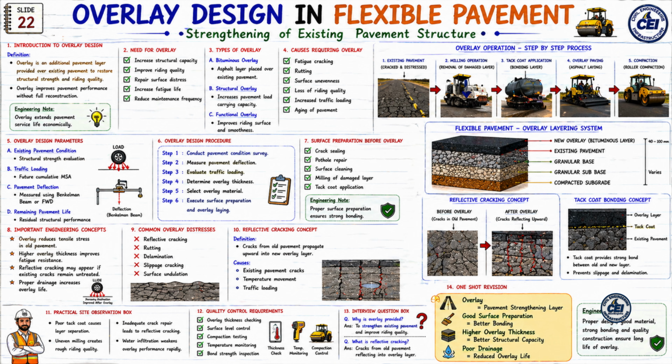Now let us look at the second topic. No need for overlay. Overlay needed. Increase structural capacity. Improve riding quality. Repair surface distress. Increase fatigue life. Reduce maintenance frequency. And these are the most common reasons for providing overlays in practical highways.